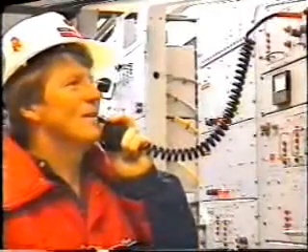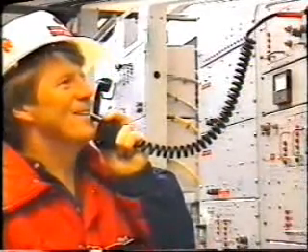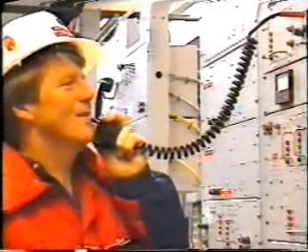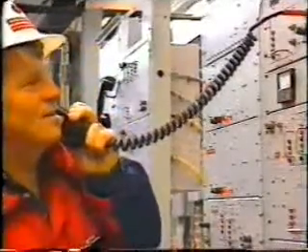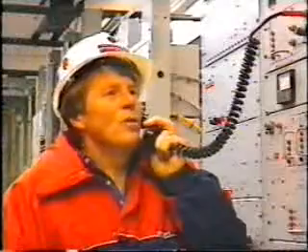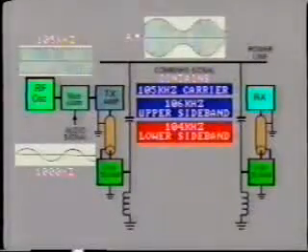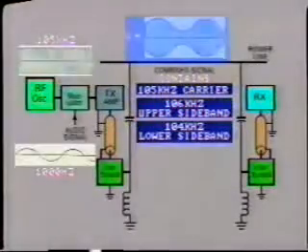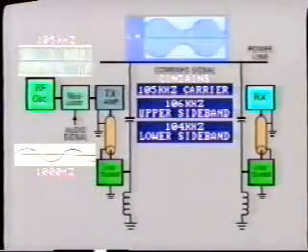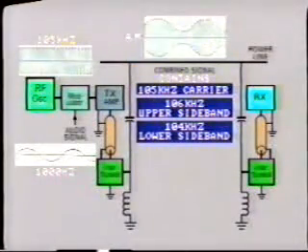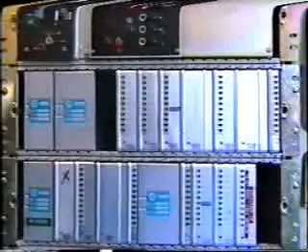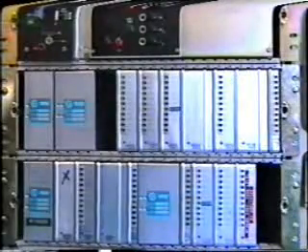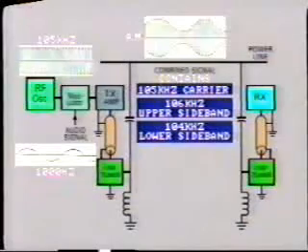With voice modulation, these upper and lower frequencies will be changing all the time within, say, 3 kilohertz up or 3 kilohertz down from the carrier frequency. The lower sideband is actually a mirror image of the upper band, just like the modulated signal envelope that we looked at. But only one of the sidebands is actually used after demodulation. So why do we need to transmit both upper and lower bands? Other people asked that same question and came up with the single sideband system.